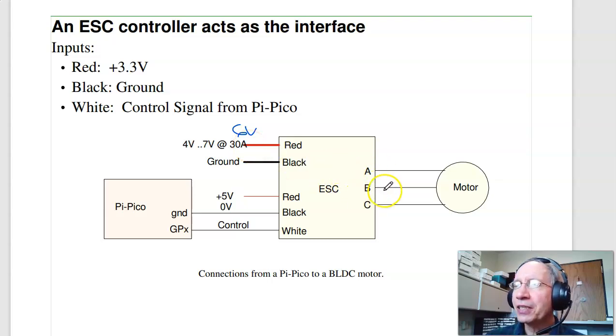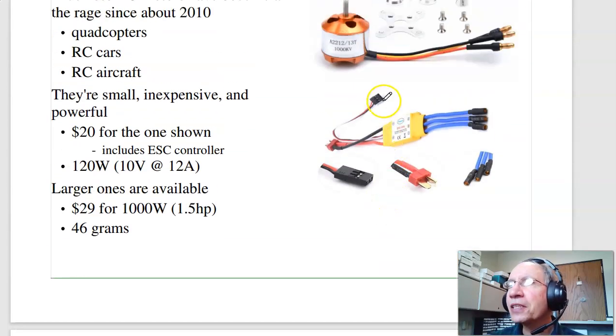The 3 leads go to the motor. They're fairly thick. It's going to be drawing a lot of current. And then there's a small wire. That's this guy right here. Again, the thick wire, that goes to motor. This goes to power. You can kind of tell because they're thick wires, it's going to draw current. These are small wires. There's no current. That's just the control signal.